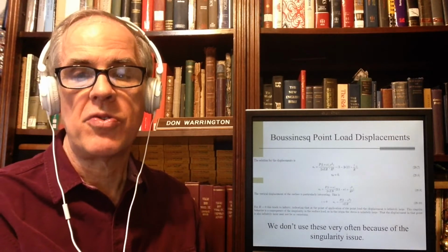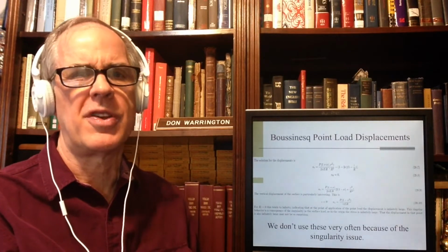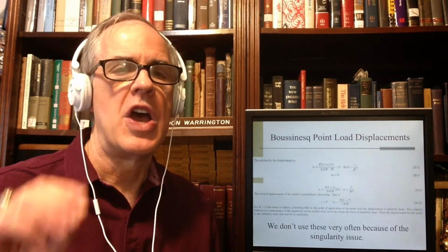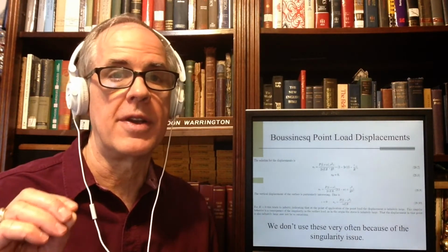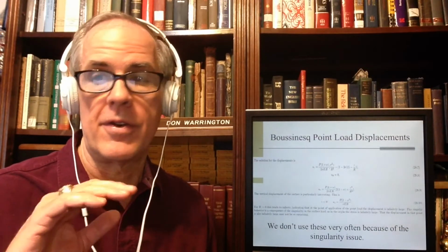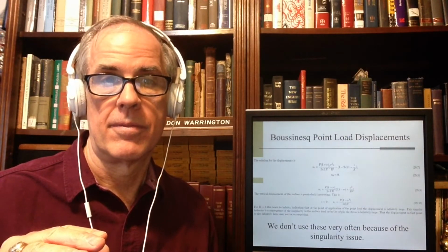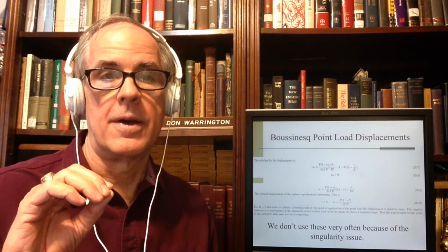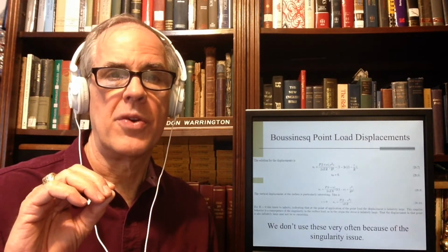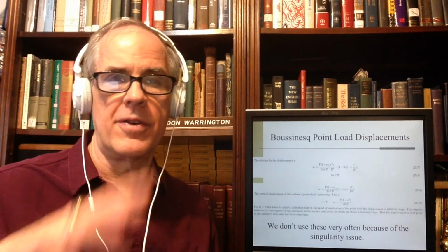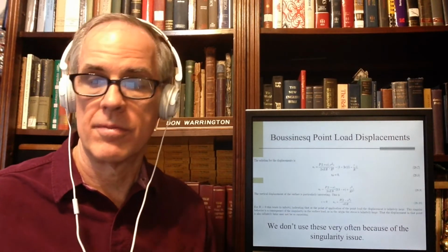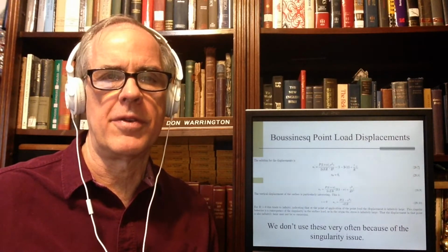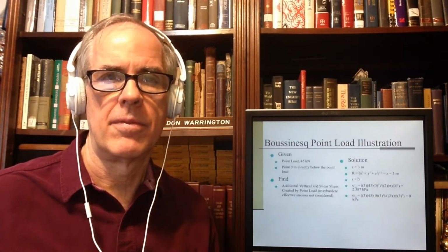We don't use these often because of the singularity, because usually if we're interested in the deflection issue, our interest is normally restricted to the foundation itself, right under it. And so we don't normally worry about the deflections of areas under the foundation. And since it blows up, we don't use the deflection equations very often with point loads.